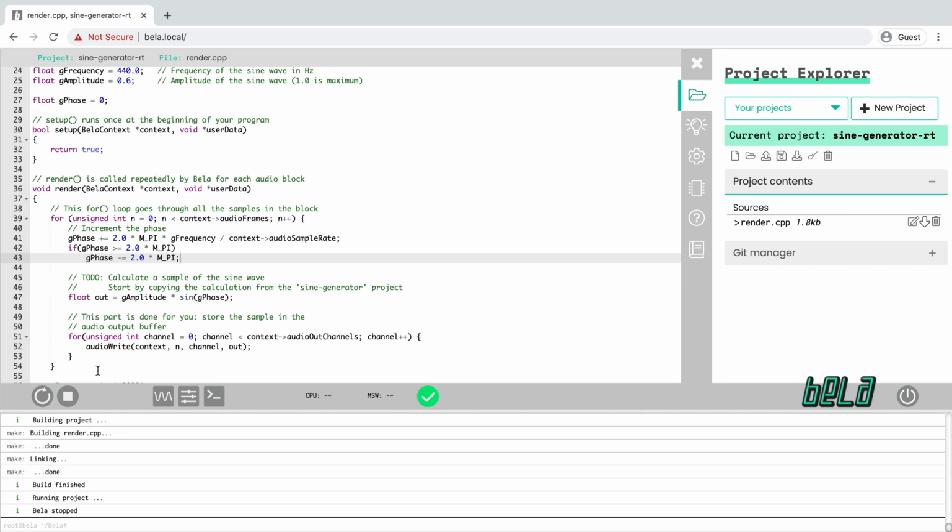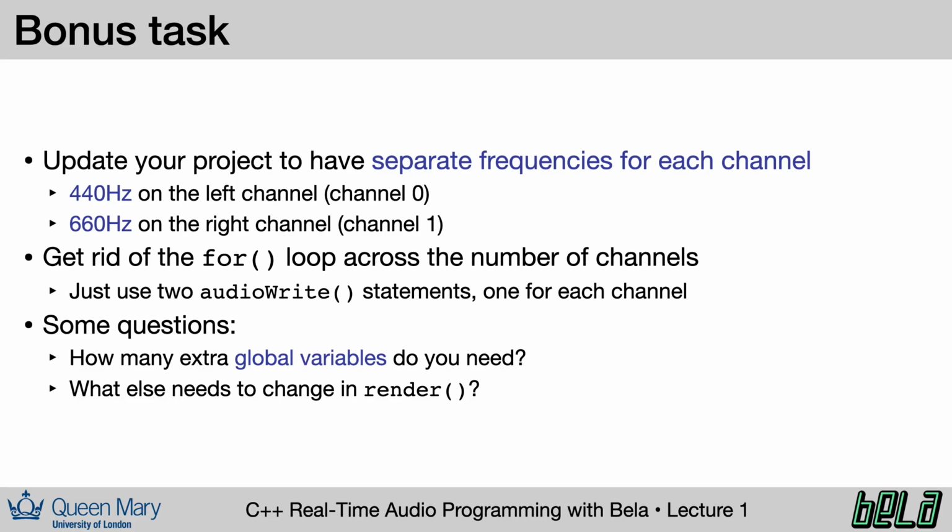So there we have it. We have taken code that was originally not in real time and we have adapted it to run in real time. And the crucial ingredient for making this happen was to remember where we left off, because the render function is only calculating one tiny slice of time for our real-time signal. And every time the render function runs, it is up to us to remember where it is that we left off and pick up from there the next time round. And what we're going to see in the ensuing lectures is that this principle of remembering the state applies very widely across real-time DSP systems.